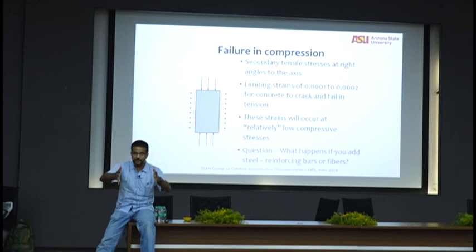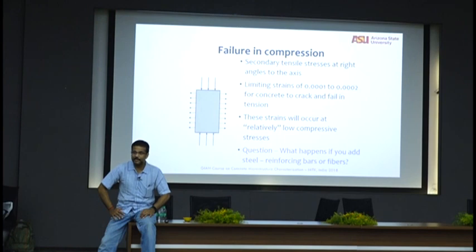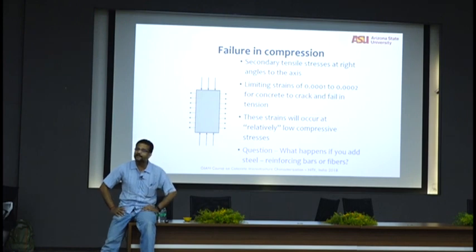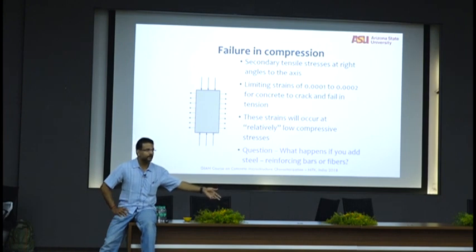You think of a concrete cylinder or a cube with aggregates and cement paste, and at some little spot you have, remember, strain is a point property, right? Stress is a point property. These are not bulk properties. Like I told you in one of those classes, we average for convenience. We average for our own ease in representing a single number. If I sit right in the middle of this table, you can use my load and whatever the support conditions to calculate a flexural strength, right? Does it mean that flexural stress is the same all through the table? No, right? You know where the location is.